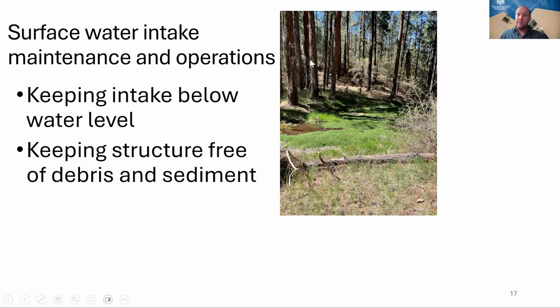So there's not as much vegetation holding in the sediment. And so regularly all of the sediment flows down and clogs up this infiltration gallery or the stream above it. And so water can't sufficiently flow through that sediment into these perforated pipes and into the treatment system. So they have to go in here with a backhoe all the time and dig all this out so that they can get sufficient water into their system.